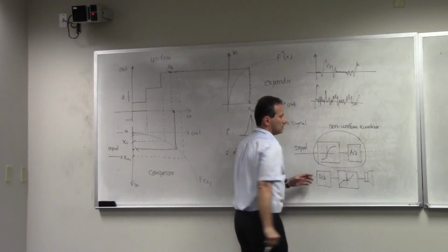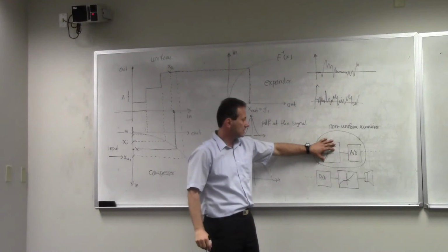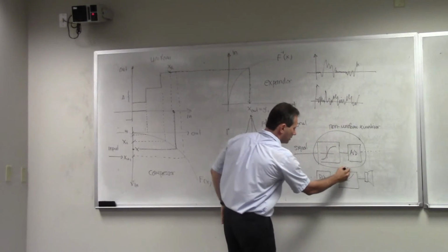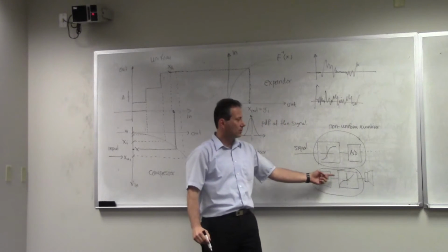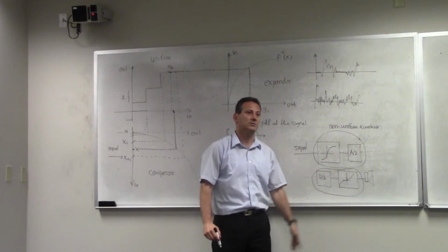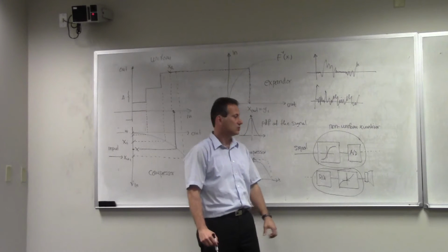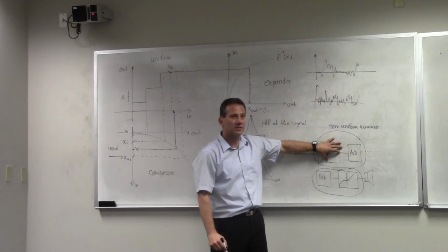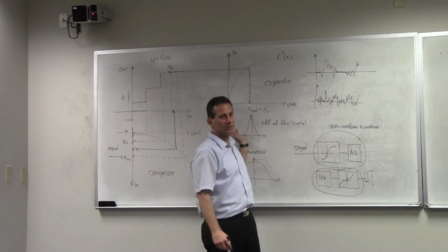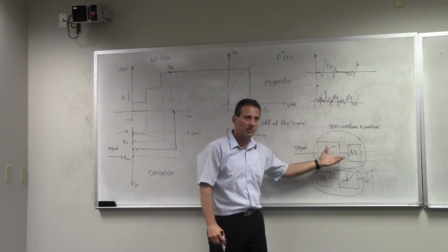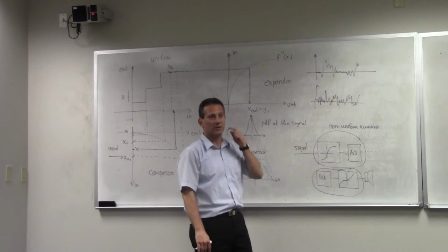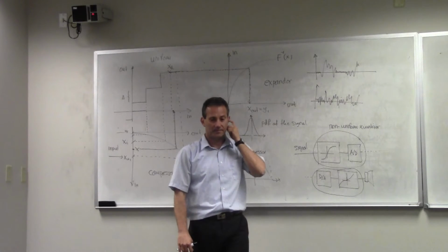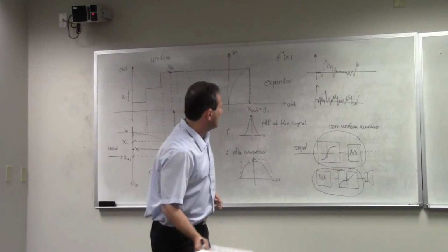Right? These two are non-uniform quantizer, and then these two in parallel, in series, actually perform digital to analog conversion when you quantize with non-uniform quantizer. So although I have them as separate blocks and separate functions, they actually together perform a function of a non-uniform quantizer. Okay? All right.